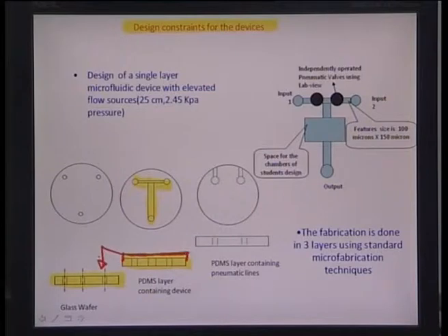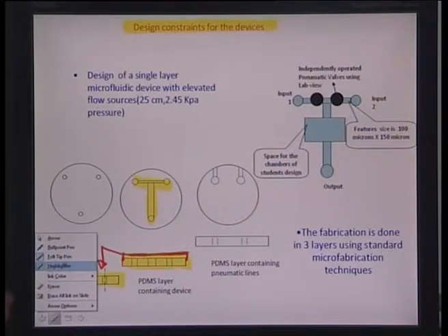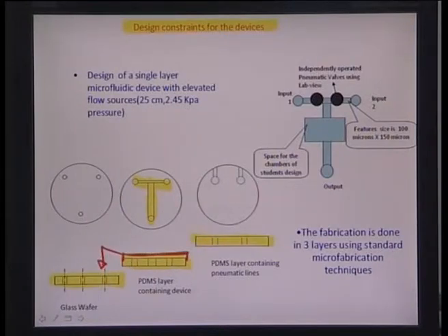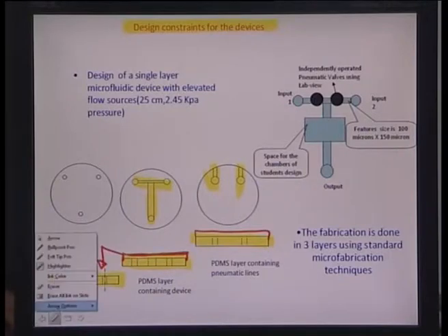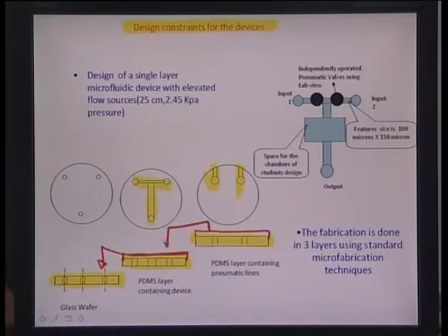Then further you have another layer where you have these blisters, the third layer, and in this particular layer again you have a certain thickness of PDMS over the blisters. The blisters, as represented here, are actually air pockets, and this further is bonded back onto the top of the first PDMS layer. Okay. So you have a stack of 3-layer devices.